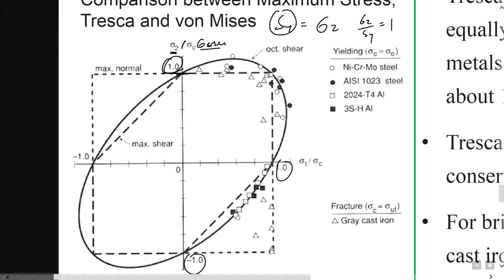If stress 2 exceeds, then you have 1.5, something like that. For example, 15 divided by 10, you have 1.5. It's 10 over 10, and it's simply equal to 1. For different ratios of the stress input, you have a different stress state, showing that you are safe over here, or you may be safe over here, and things like that.